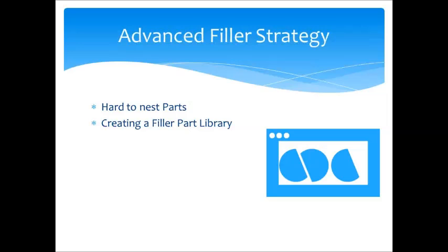A filler part library is a group of parts that we've identified that are great companion parts that we're willing to time displace. Now remember, the definition of a filler part is a part that will be cut out of scrap. So you have to adjust your thinking here a little bit to recognize that while we might time displace or advance the production of a filler part, it's only going to be cut out of scrap, so it pays for itself in material for what we do with it in terms of advancing the schedule.